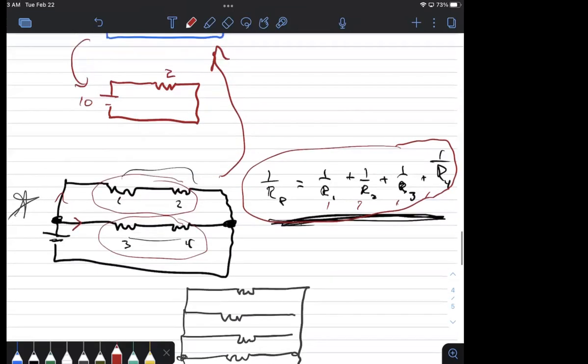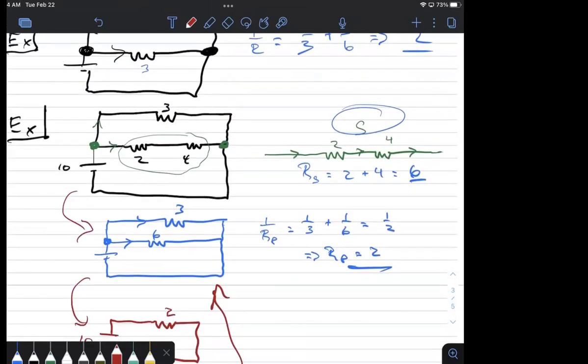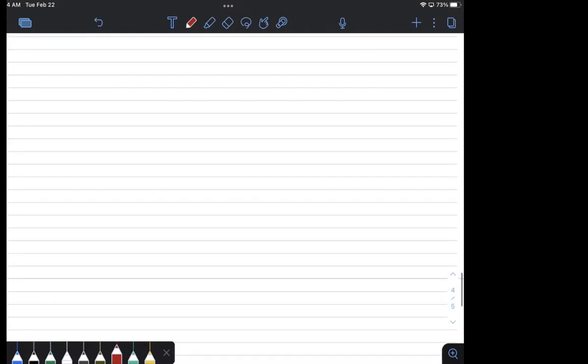And for me, it's just kind of a feeling you get when you look at the problem. When I look at this first example with the 3 resistors sitting here, I say, okay, I know I have 2 branches which are parallel, but before that parallel thing, one of the branches is already in series. So take care of the series first. Once I take care of the series, now all I'm left with is the parallel by itself, and that's what I want. What I've seen in the past, I see it every semester, is, let's take this example and I'll redraw it just so it's a little cleaner. I'll see this example.